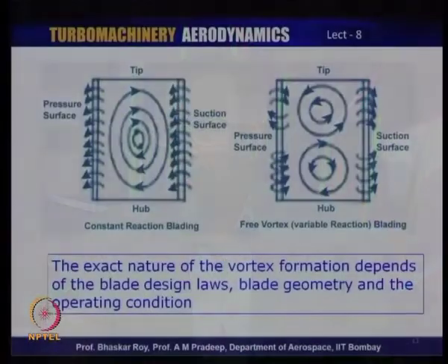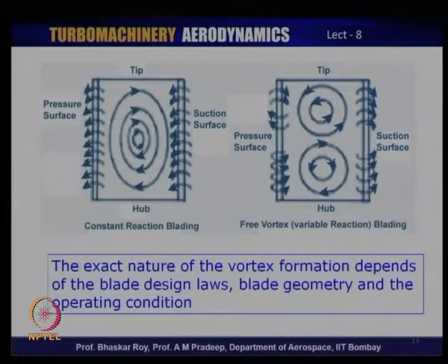You see, we have talked about before, the blade is designed at a particular operating point, which is known as the design point, but the engine and the blades, the compressors would have to operate under various operating conditions, where the speed of rotation RPM and the mass flows are different from the design point. So, an operating point away from the design point would indeed impact on the vortex formation. The vortex formation depends on three things: design laws, blade geometry and the operating condition at which the blade is operating.